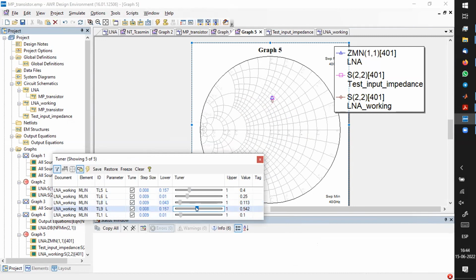Remember, you always make it narrowband if you go there. Remember the Q circles. So you want to maybe stay below. So what we could do is plot the S opt circles, if you go far away, which I have in the slide set. It's good there for a while. We can tune it later. We need the output matching and we want to see how it looks.